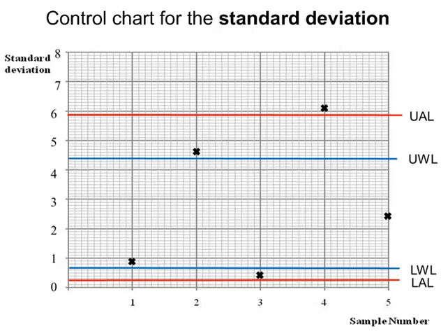Here is a control chart for standard deviation. And standard deviation is measuring the variability in the production process, and a low variability is desirable. So values at this end are desirable and not at this end. There is no set target limit for the standard deviation. If there was a target, it would ideally be 0.